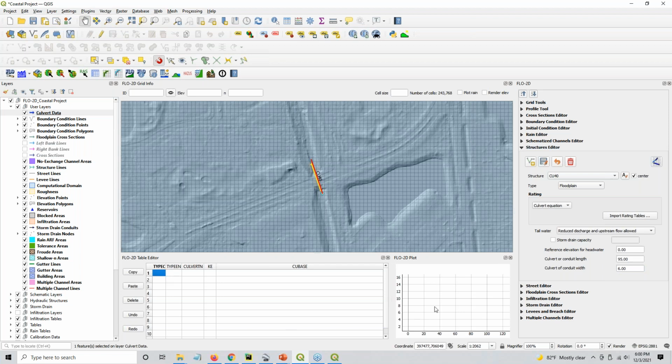And again, it's a box culvert, so that's a 1. The entrance type is 3, so I think that's 30 to 75 degree wing walls, 0.012, 0.5. And the base of this one is, again, 11. So again, I don't think that's 11. I think it's 10. So I'll just set that to 10 because I've never seen a 6 by 11 box culvert. I've seen a 6 by 10 or 6 with 2 5s or whatever.